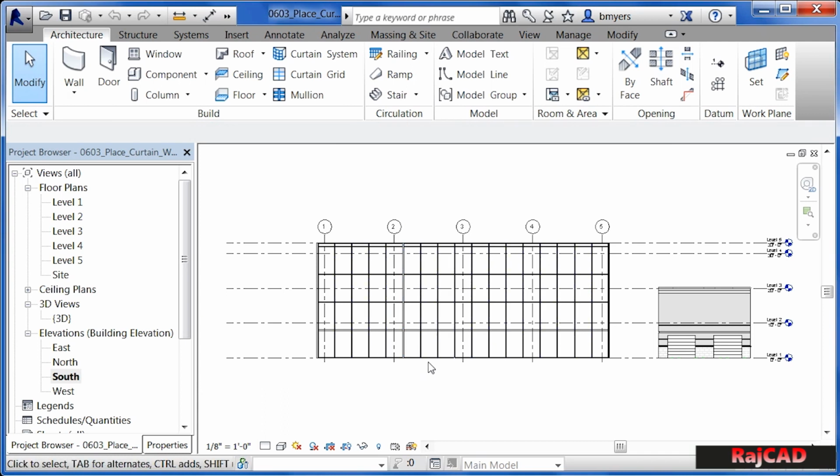Where I'd like to place a door in will be right in this panel right here. I'm going to move my mouse up and then highlight right where that panel is at, and then click the Tab key. Now for some people, this might start to tab through and be able to highlight the individual panel as I highlight over that line and then hit Tab. In my case, it's making music. What it's trying to indicate to me is that this is currently locked or it's currently pinned down.